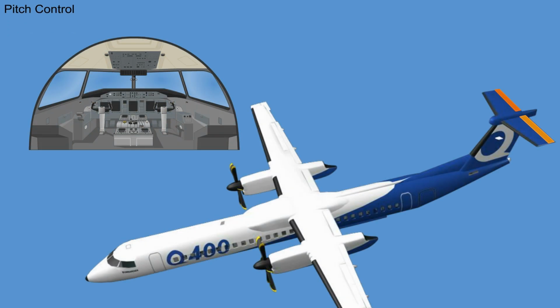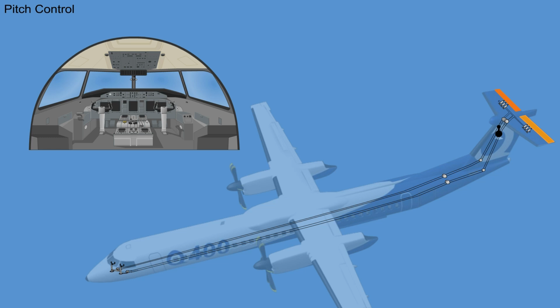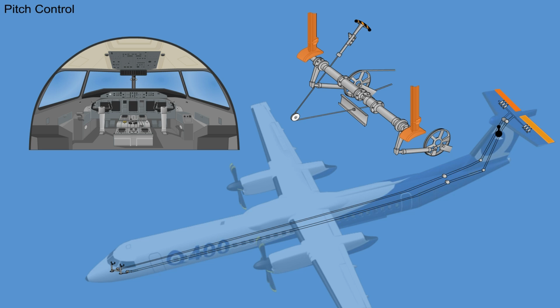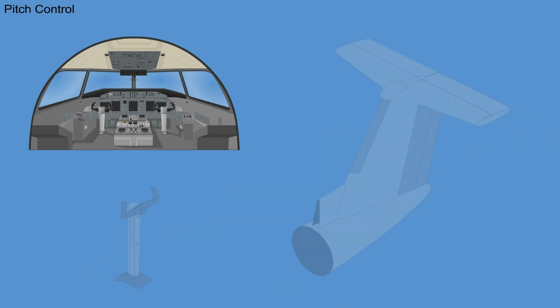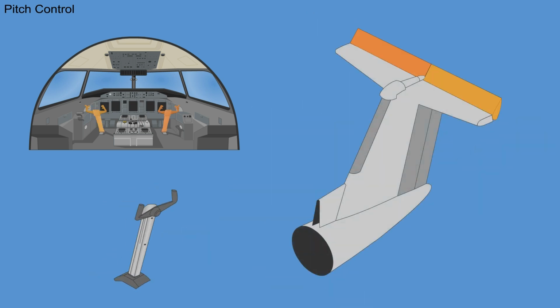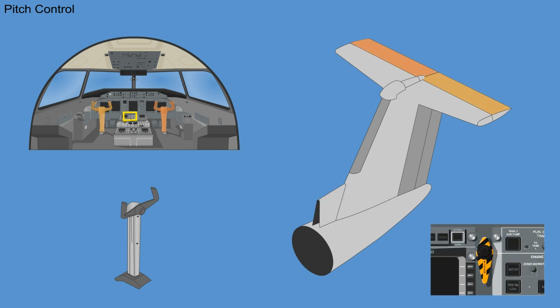Pitch control of the aircraft is maintained by two independent mechanically controlled and hydraulically powered elevators. The pilot's control column operates the left elevator, and the co-pilot's column operates the right elevator. The two control columns are normally interconnected by a shaft. Simultaneous movement of both elevators is provided. In the case of a jamming elevator, the two systems can be disconnected. Limited pitch control is then provided by the remaining elevator.